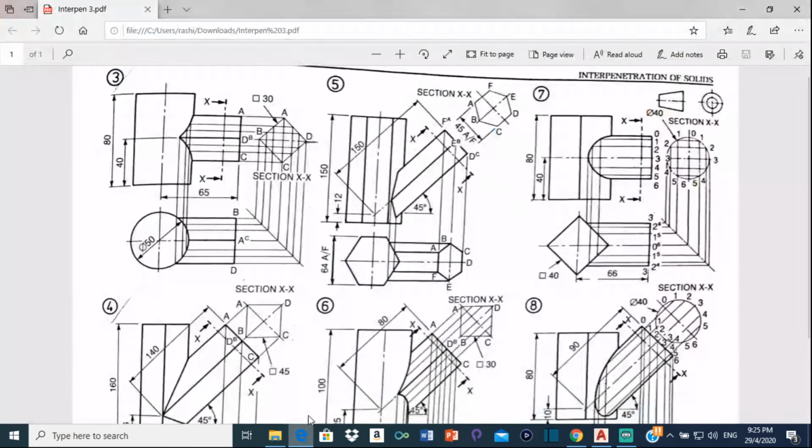Alright, now if we look at this drawing, up here, this is AF right here, and this is AF down here. So we're seeing the true length of AF here. Since we're looking down on it, we're able to see the actual true length of AF right here. So since we're able to see this true length, we can measure AF here, and we will know the distance of AF down here because it's the same thing. Alright, so let's do that.